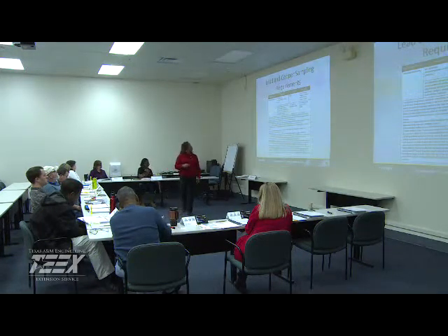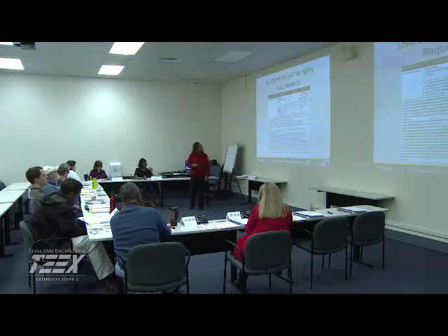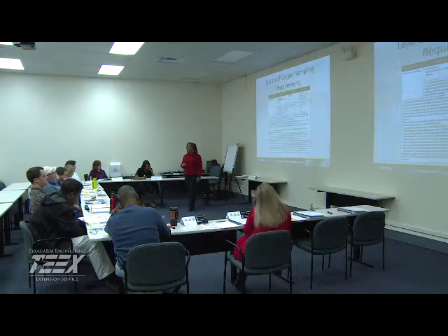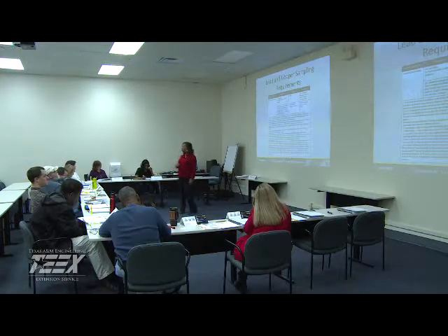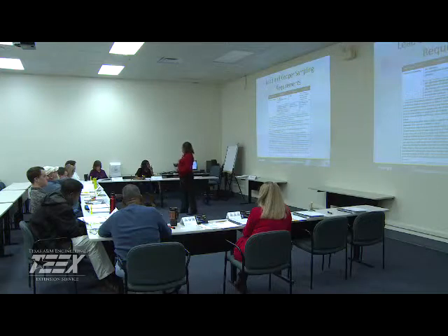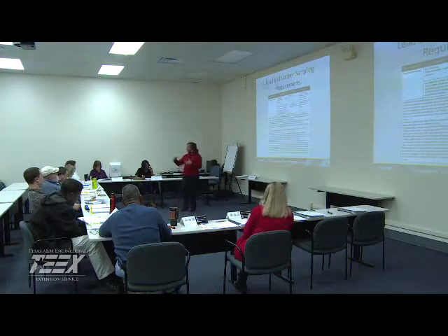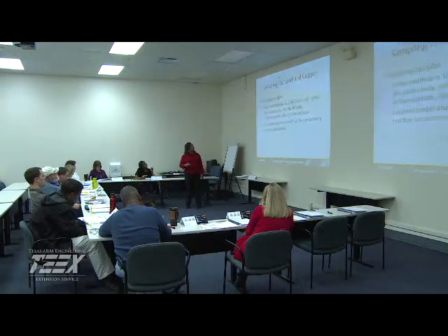For reduced monitoring, if we're on this game plan here, every 6 months, annually, or it can be every 3 years, you may be given a reduced number of sites. And what we'll see when we start looking at the chemical contaminants, depending on what's in your system, that can be reduced even longer, up to 9 years.